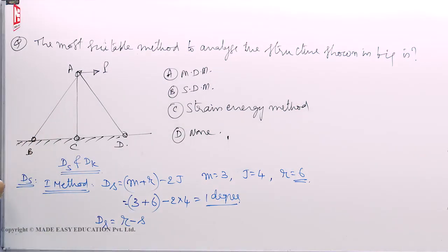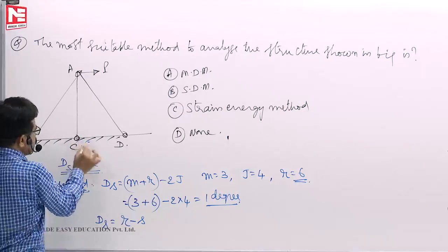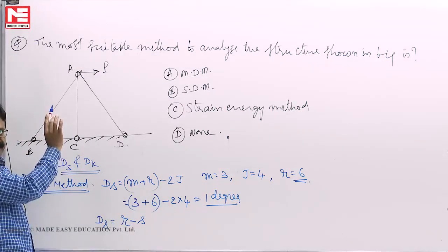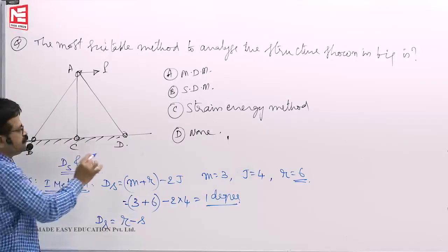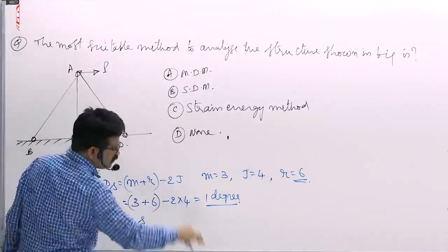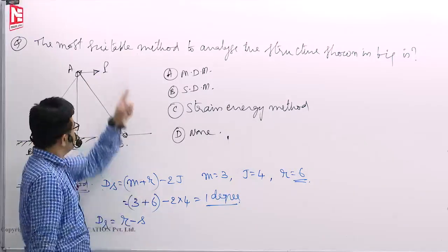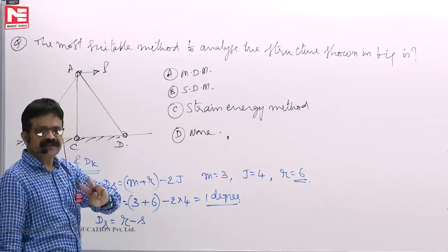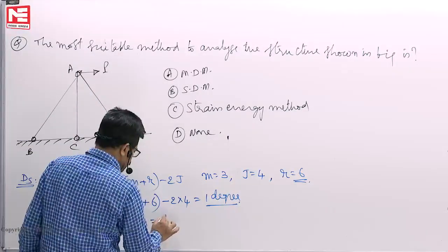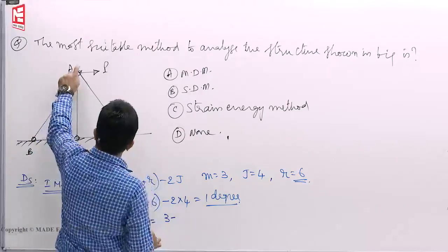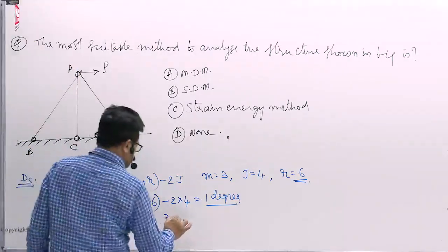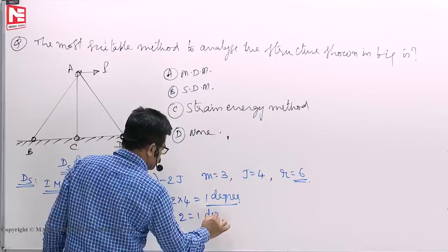It has to be in the line of the member only. Here, HC, VC resultant has to be vertical only, HC must be 0. Then VD, HD resultant reaction must be along AD only. So, total number of unknowns are actually 3 only. If I take unknowns as 3, equations of equilibrium is joint equilibrium 2. You will get 1 degree.